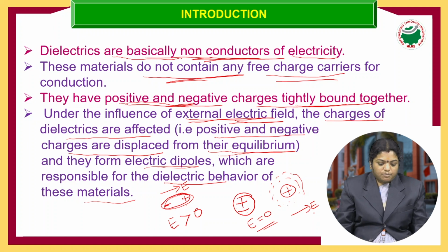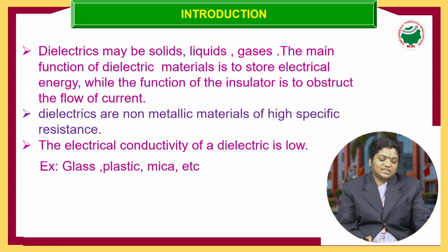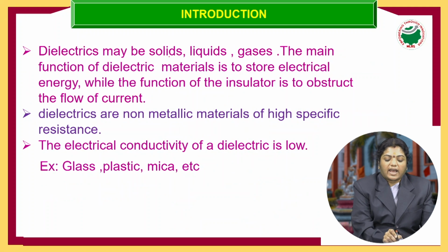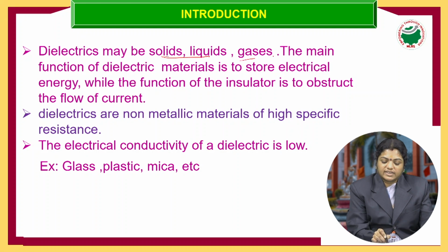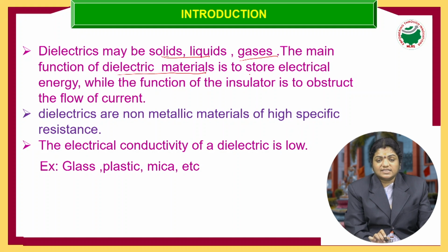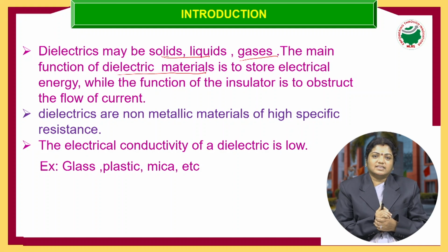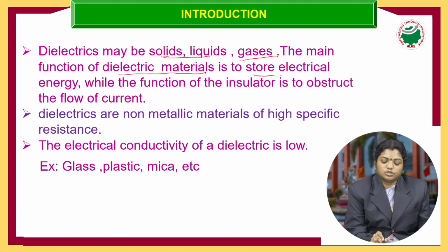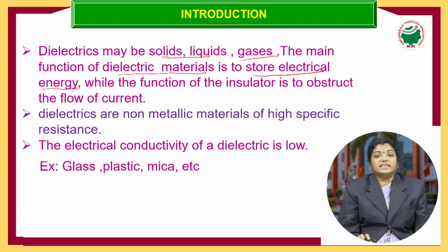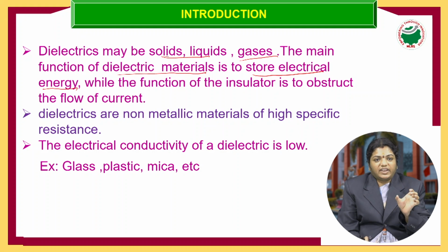This is about some points. Next, the dielectric materials. Dielectrics may be solids, liquids and gases also. What is the purpose of dielectric materials? Why do we use dielectric materials? The main purpose is to store electrical energy in the presence of the electric field. Whenever we apply the electric field, some dipoles are created, and due to that, electrical charges are stored.